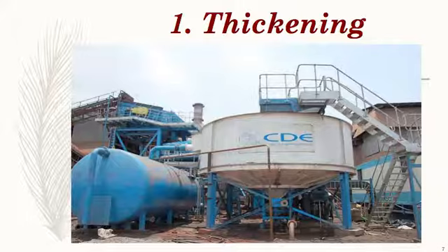Sludge from the primary or secondary sludges may be stirred, often after addition of clarifying agents, to form larger, more rapidly settling aggregates. All of this is carried out in a large mechanical machine in which there is a settleable material along with the addition of clarifying agents to form the settled larger sediments or sludge aggregates.